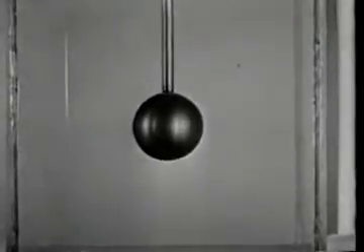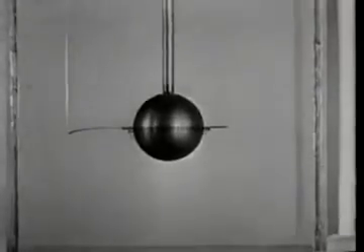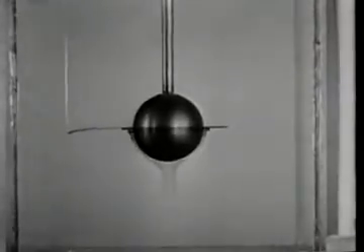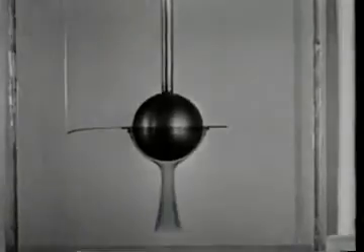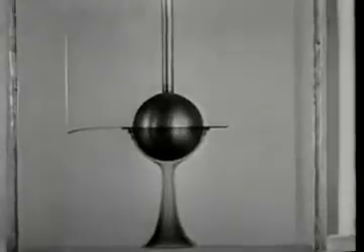When plastic articles are to be made by the extrusion process, the die must often be designed smaller than the dimensions desired in the finished product. Here, a sphere is rotating in a high polymer solution. Dye, introduced at the left, reveals the flow spiraling inward at the equator and outward at the pole. For a Newtonian fluid, on the other hand, where centrifugal forces are dominant, we would look for flow inward at the poles and outward at the equator.